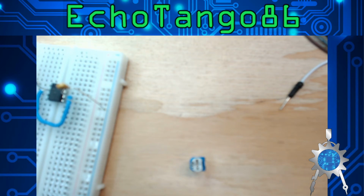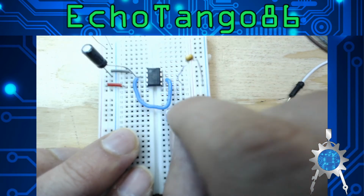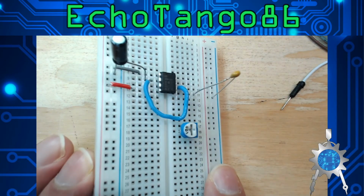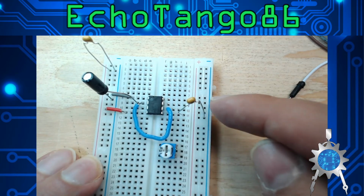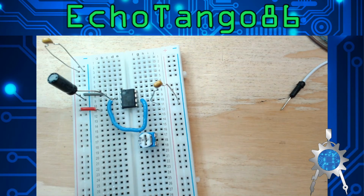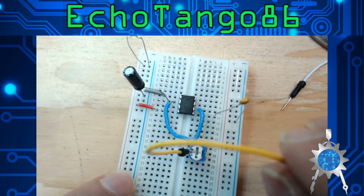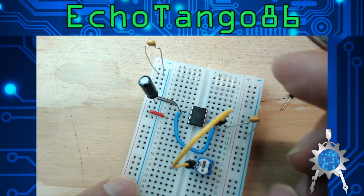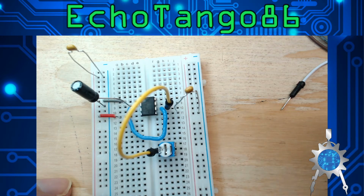Now, depending on how you're wiring it up here, it might be better to put the resistor just kind of down here, because it'll make it to where you don't have to worry about connecting up the pins, because you don't want to have it run into this pin and it makes it a little cluttered up there. So what we'll do is we'll put it in here, and take that one and we'll go to pin 6, which is up here. Pin 6 there. And then we'll grab another one.